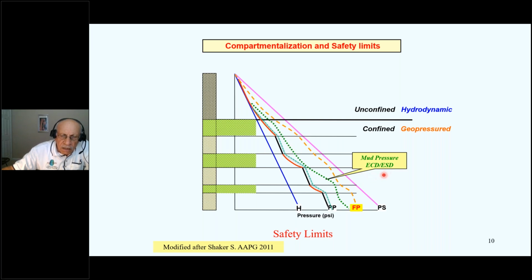And the mud here, measured in ECD or ESD, either static or dynamic. The dynamic means in the movement. The mud is moving, going from the drill floor down to the drill bit, coming back. So it has the pressure of the pump added to the static.